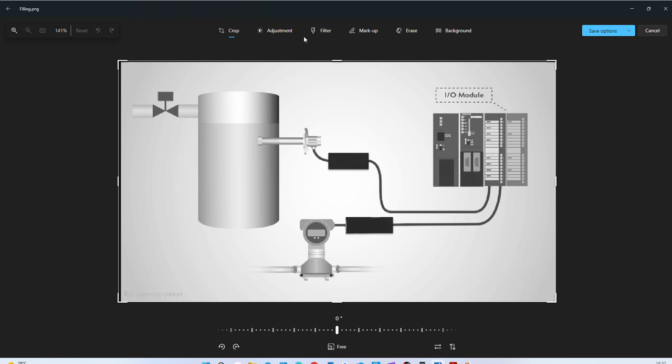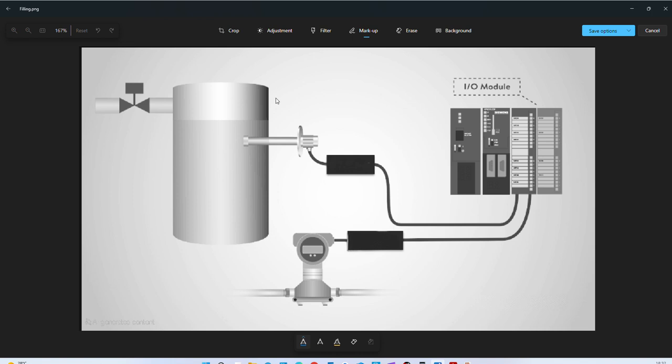So in that example, we'll have to do scaling of the variable in terms of the analog, and then we're gonna do a control of this digital signal using the set points that we would have agreed upon in here. So what we are saying here is at 80% we close, and then at 20% we open.